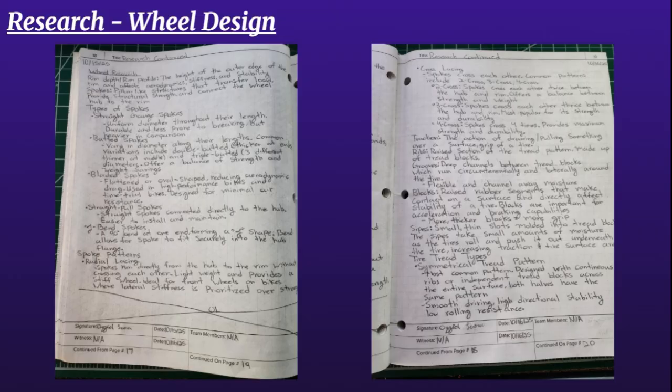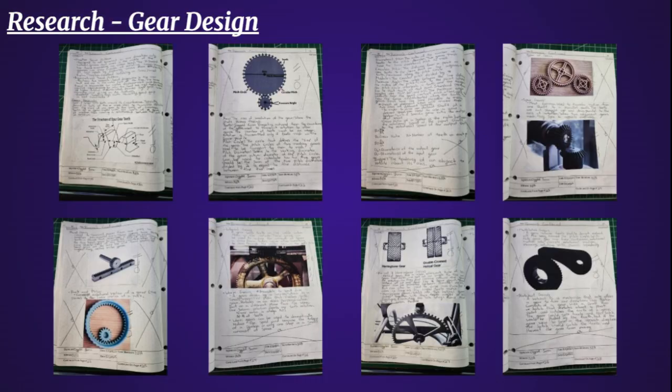To avoid potentially not gaining enough traction, my wheels need some kind of blocks or sipes tread patterns. I decided to go with straight radial lacing spoke patterns combined with a symmetrical groove tire pattern with bladed spokes. While bladed spokes would have been the best, I decided against it because I feared that the 3D print residue would harm the inside of the wheel. So, in order to be safe and keep the wheel moving smoothly, I went along with the straight spokes, something that I knew wouldn't leave residue.